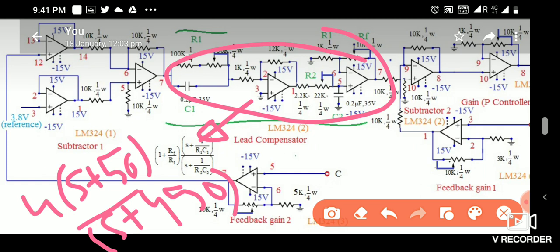design the circuit. Now these are all LM324 op-amps. You can also use the TL084 op-amp, but the properties are different. You will have to check from the data sheet what the operating point is, etc. Generally, in LM324 there are 4 op-amps available in one IC.